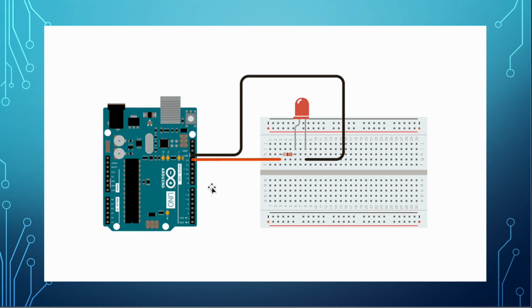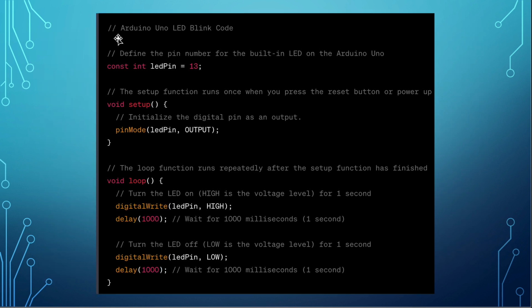So in that particular case, you can approach it in different methods. For example, you can start with the LED bulb, see if it is working, then you plug in the next hardware component. Then you can't use the same port because it's already in use, right? So you have to draw the circuitry, you have to understand the circuitry, then you have to again define, let's say a servo motor is there, so we have to define that pin.